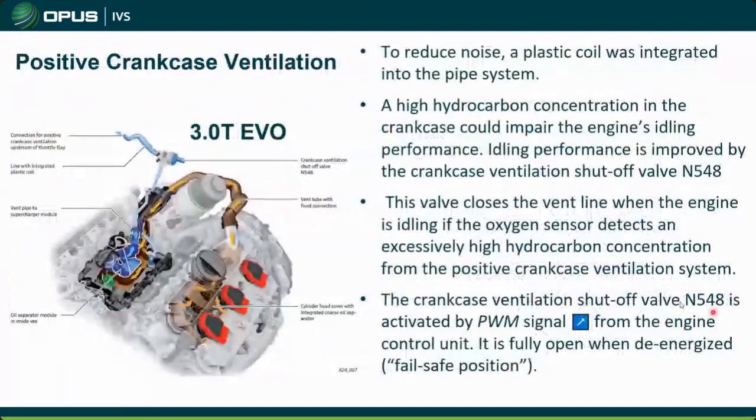Something else to note on these is that this vent tube here is insulated. Now, remember when I was talking about Mr. Freeze back there and the dust off? The reason that they're doing this is because when you have water in this system, in these swirl chambers and in these check valves and everything, it doesn't take a lot of water to freeze up in order to prevent a valve from opening, or maybe prevent it from closing, or just in general messing with the system.